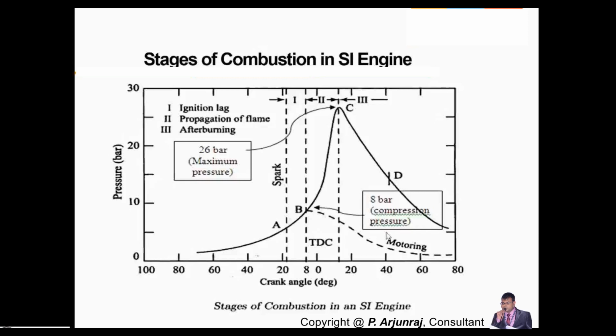What we can call this as the speed of the engine or the torque output. The power is going to be lesser. The speed and the torque is going to be lesser. It means you cannot expect the required relevant speed or the relevant power for the particular engine. So here they have mentioned the compression pressure as 8 bar. And again it's not going to be exactly at 8 bar. It will vary from engine to engine, and all depends on the engine configuration.